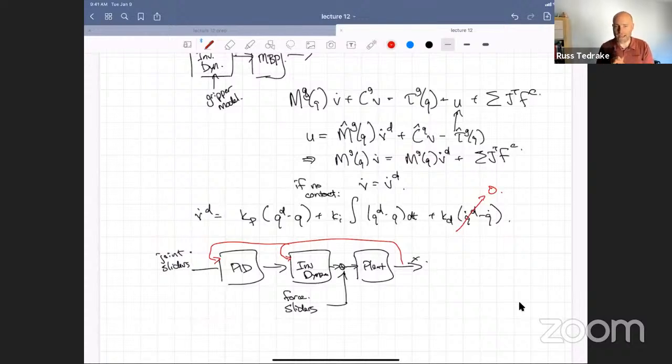Okay, and that is actually an interesting way to think about how to flip these boxes up, and we'll talk about it. There's the impedance control view of the world, which is that you should actually program the compliant interaction between your robot and the world, and treat the world as roughly unknown. That is sort of what the interface we're giving you here is. But that's a pretty indirect way to think about the forces you're applying.